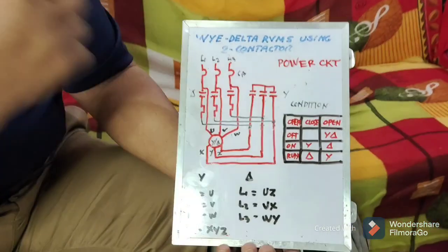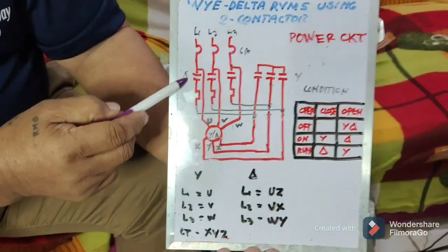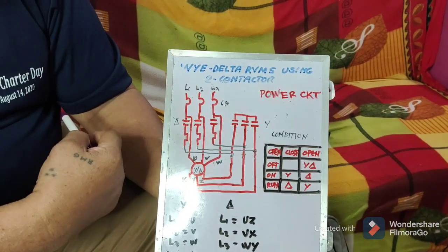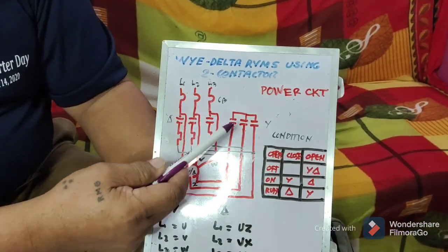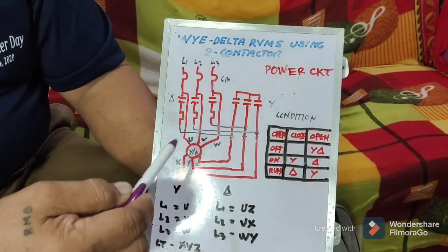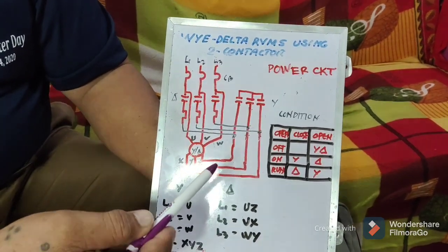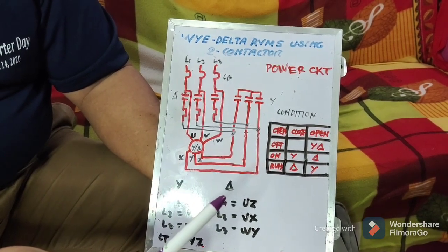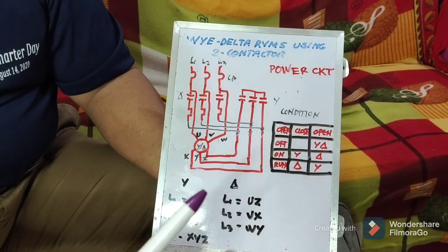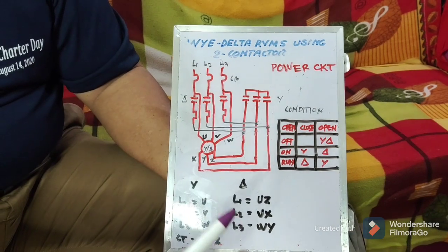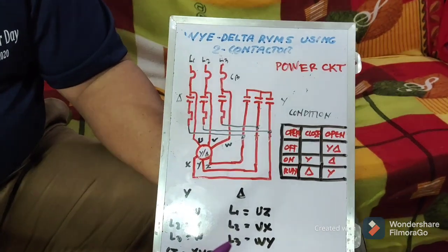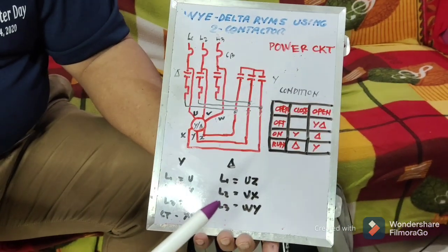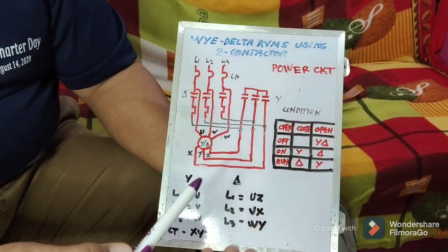power circuit. So we have here the delta, and then we have the Y contactor. Now always remember that the Y contactor is only intended for short circuiting. It always short circuits the XYZ, that is in the European, and in the American you have to short circuit the 4, 5, and 6, because these are all endings.